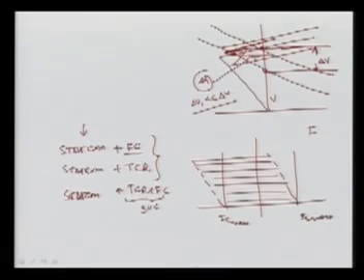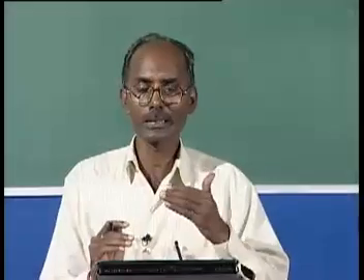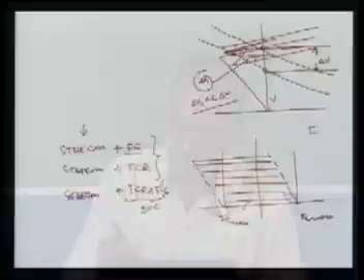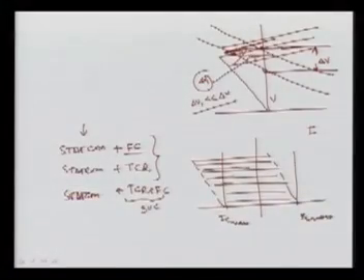What is the advantage we are getting? Most of the time, if the voltage is low, we want reactive power support. In this zone we now have this final characteristic, which is larger, and this system is better compared to the STATCOM alone.